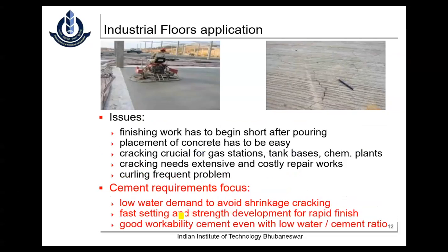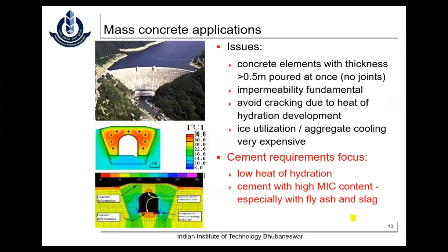So when it comes to mass concreting applications, definitely when talking about dam construction or a mass concreting application where you're going to use a huge volume of concrete in a single pour, like raft foundations, pile rafts, sometimes the pour goes up to 2, 3 or 4 days. Continuously they pour the concrete to avoid the cold joints and all this. There the requirements are different.